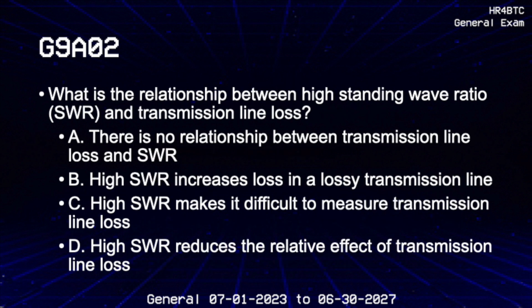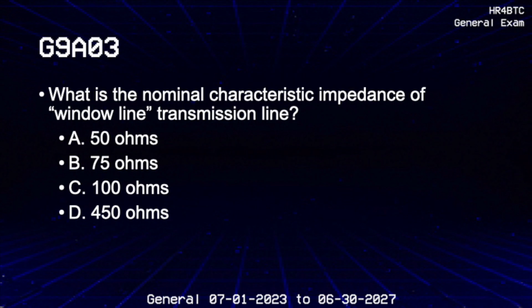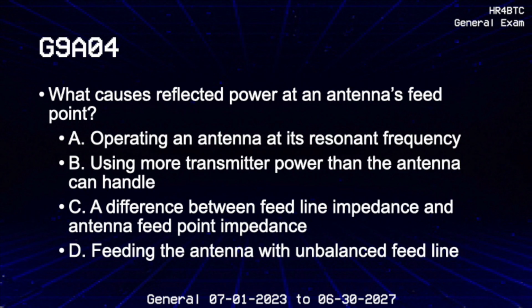What is the relationship between high standing wave ratio, SWR, and transmission line loss? High SWR increases loss in a lossy transmission line. What is the nominal characteristic impedance of window line transmission line? 450 ohms. What causes reflected power at an antenna's feed point?